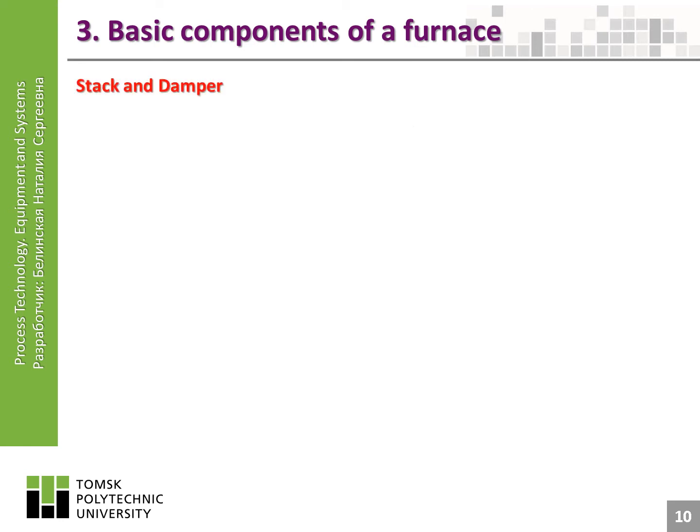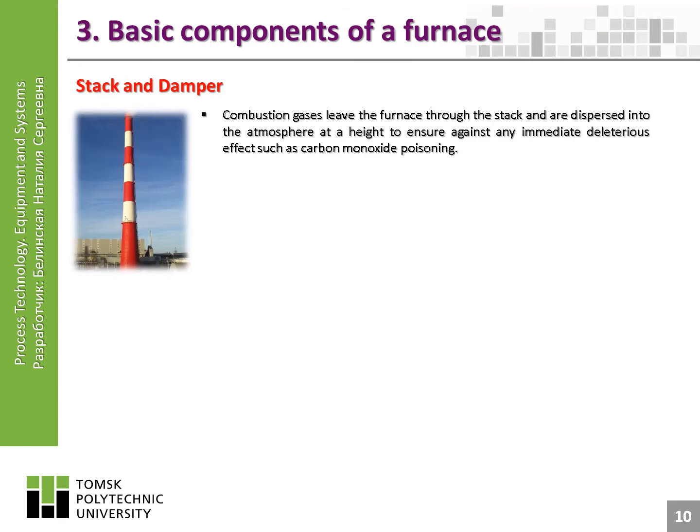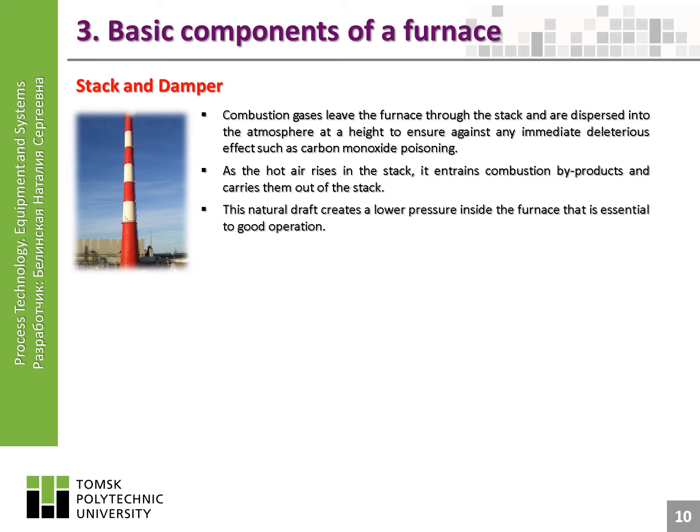Stack and damper. Combustion gases leave the furnace through the stack and are dispersed into the atmosphere at a height to ensure against any immediate deleterious effects such as carbon monoxide poisoning. As the hot air rises in the stack, it entrains combustion by-products and carries them out of the stack. This natural draft creates a lower pressure inside the furnace that is essential to good operation.